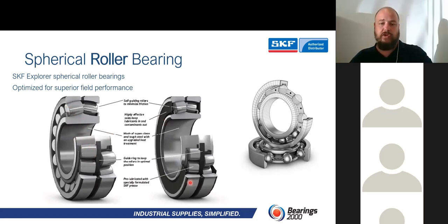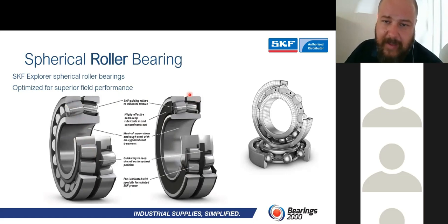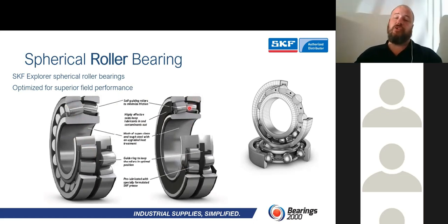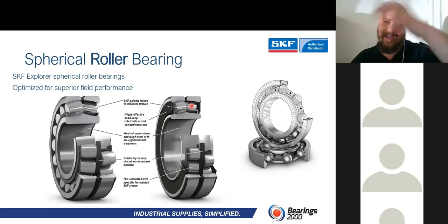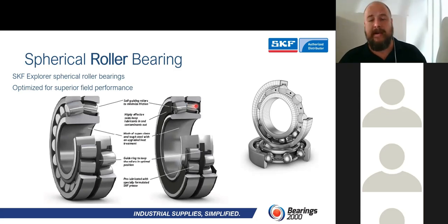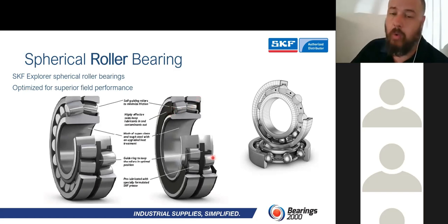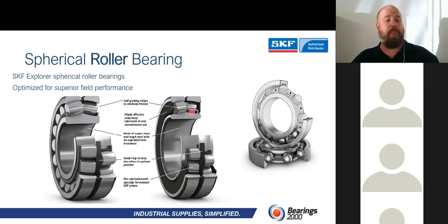The sealed units, of course, are pre-lubricated. All of them have got the W33, which is that lubrication groove over there. And what makes this sealed unit so nice is when you put it in a plummer block, you can put the entire plummer block full of lubrication around the side, and that lubrication on the plummer block actually becomes a seal. It becomes a barrier to exclude any or all contaminants. So now you need to run through the seal, through the grease, you get to a bearing and bang, bang, bang, you're bumping your head against another seal. So once you look at these units, guys, they are brilliant units.